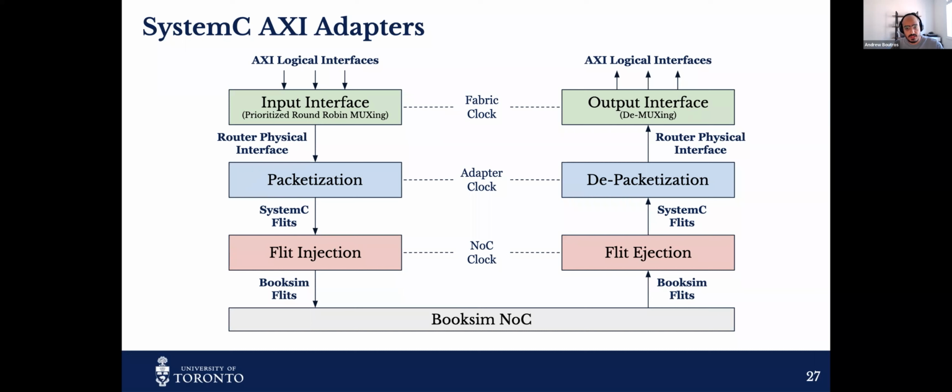We actually implement SystemC NoC adapters that follow the AXI streaming and AXI memory-mapped protocols. So right now in RAD-Sim, the user can just hook up any module that abides by an AXI interface. But we also build this in a way such that if you want to experiment with other protocols, you just need to implement your own adapter and plug it into RAD-Sim.